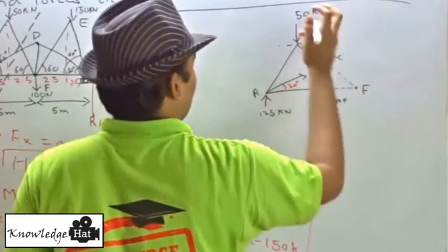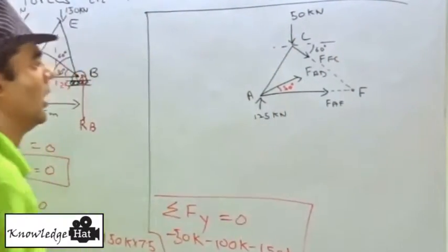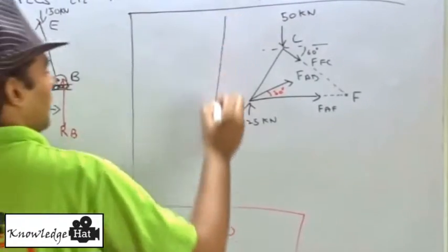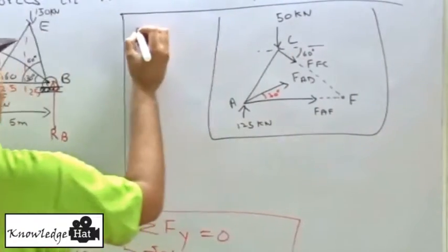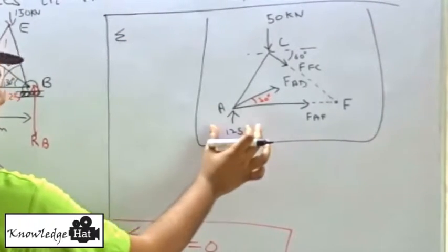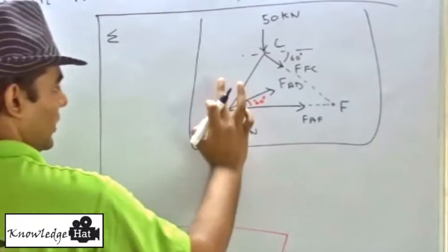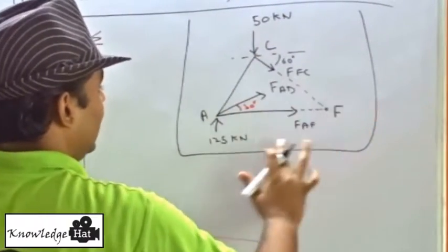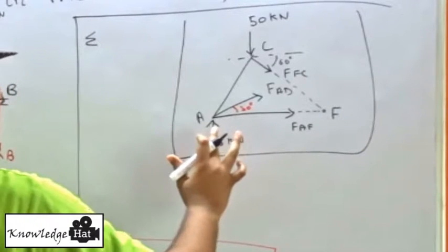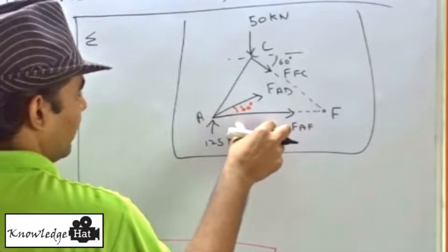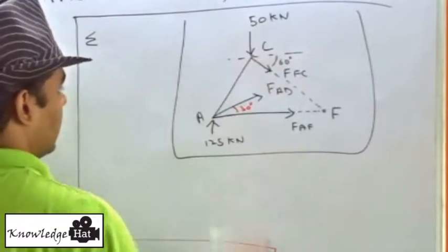Now we'll take this as an entire system and we will go about solving it by our normal equilibrium method, taking summation. Now we'll think this is a force in upward direction, this is a force in downward direction. We don't have any known force in horizontal directions as of now. So we'll first take, we have one unknown here, this is also unknown and this is also unknown.